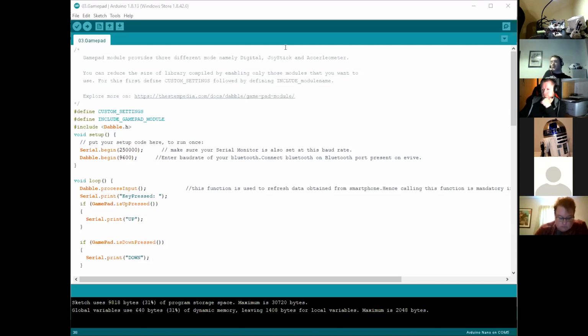Rightio. The problem is that the servos work on milliseconds, so 1,500 microseconds puts a waveform that puts the servo dead center. Now the Arduino doesn't work on those kinds of timings, and it can be affected by what else it's running. It's also a fairly sluggish processor, and what you're asking it to do is time something accurately every millisecond. So the Arduino does struggle with that.